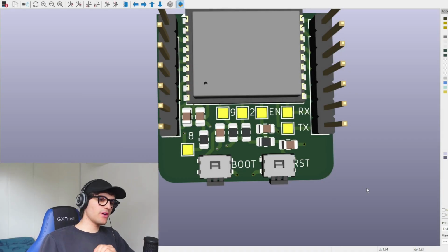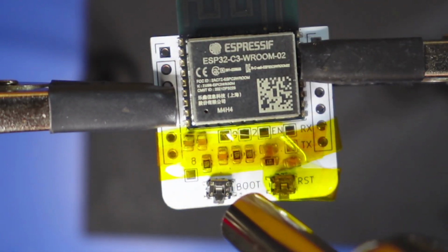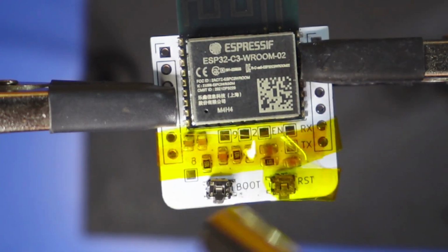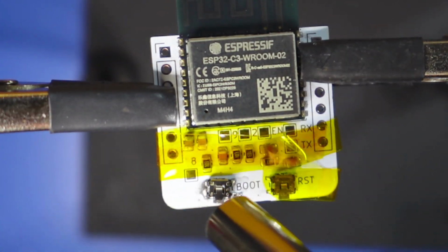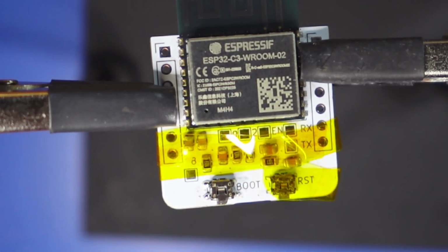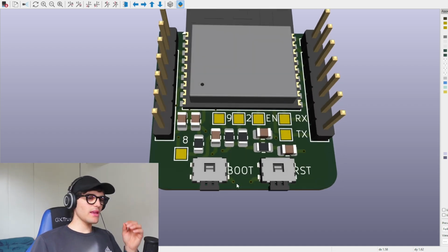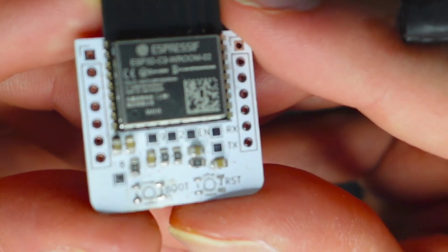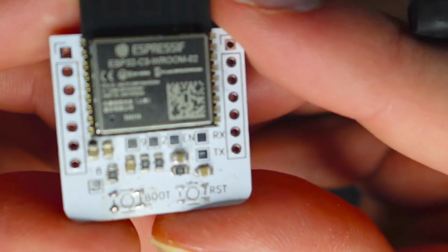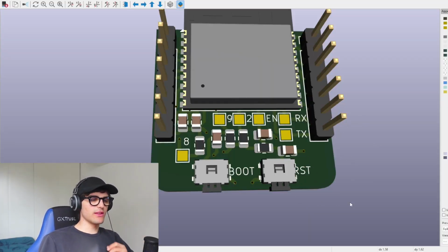The second mistake that I've made, as you can see from the video, is that one of the buttons wasn't really soldered correctly into the board, and so I had to re-solder only this button right here. But then while I was soldering the buttons, I realized that I was melting the cap of the button. Basically it was unusable. And so after burning like two of them, I decided to just get rid of these buttons, and for the next week I think I'm going to solder another type of switch. It won't surely look clean, but at least I will be able to try this board.